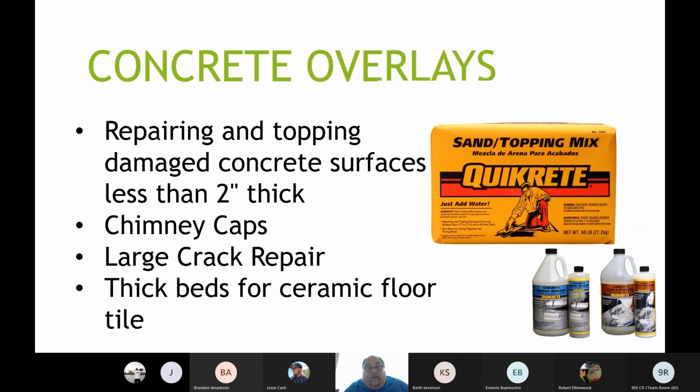It ends up being 5,000 PSI, and this is one of those products where you are going to want to use a fortifier or a bonding adhesive. You can see that's why I put the picture on that page of those two products as well. If you're doing an overlay, this is one you're going to have to float and finish, but it's the most simple product, and it's one of those products that people think they need the Billy Mays Chihuahua, some amazing material that works like duct tape. You just sometimes need something very simple that has great results, that's a good product, and this is that.